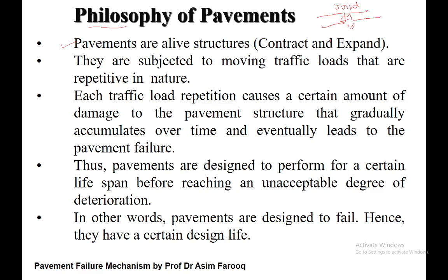To control thermal cracks, we usually provide joints. So when the temperature rises, it expands. When temperature falls, it contracts. The same contraction and expansion happen due to the cement hydration, which we call the exothermic process. So pavement could move from contraction to expansion, and according to theory or field observation, a maximum of around 30 mm expansion has been recorded.